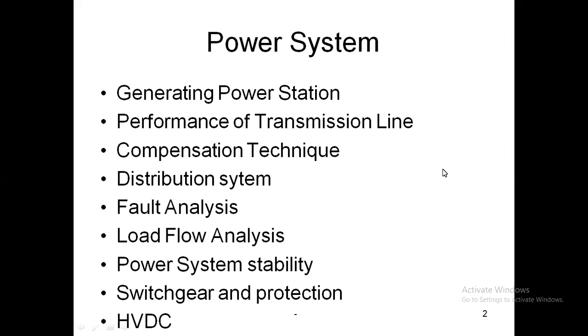And after that, the last fault is known as the line to line fault. In the double line to ground fault, two phases get short circuited with the ground, but if only two phases get short circuited with each other, then that is known as the line to line fault. That also comes under fault analysis. So these are the four faults which generally happen in the power system.